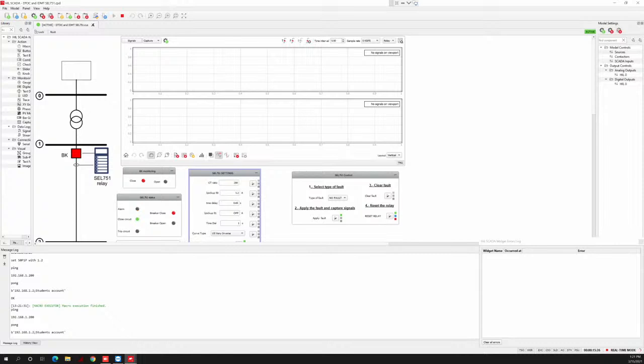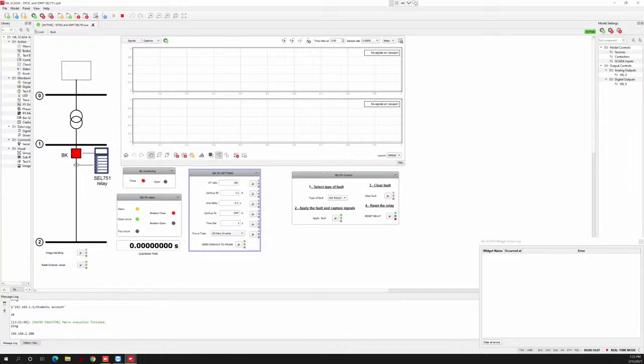with the settings. Okay. Setting done. Now we will use a defined time delay. In this case, I will use 0.3. She is using a defined time protection. That means when the current is above that value, it will take 0.3 seconds to open the circuit breaker. That is what she is doing right now, okay?